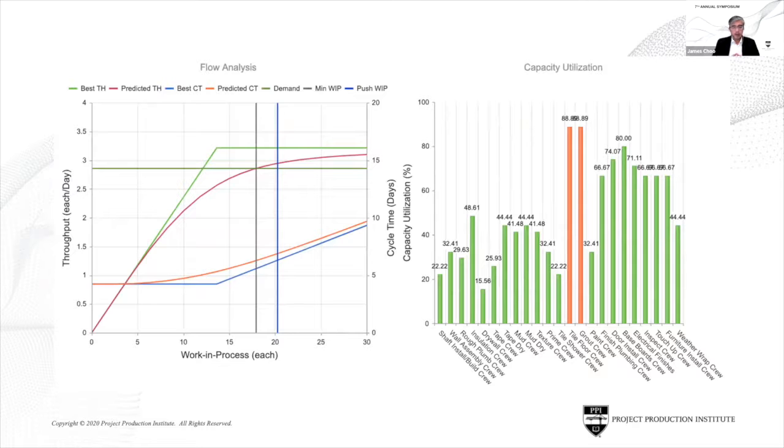Okay, and then the next one that we look at is once we have the information about the process, the rate at which each operation can be done, the amount of capacity, labor, equipment, and space that's available is put into the model, then we can start to see what is the right level of WIP we need to have in the system. And as many of our speakers have alluded to, work in process is the leading indicator for throughput as well as the cycle time, right?